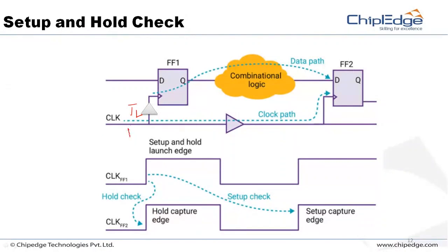So the clock has started here. The clock pulse has come here, but to reach this, it has taken some time. Then after reaching this, the data might be ready here, like 1. This should be sampled to here. It should become 1. This 1 to 1 becoming will take some time. I call this TCQ. That's the time it takes, called TCQ.